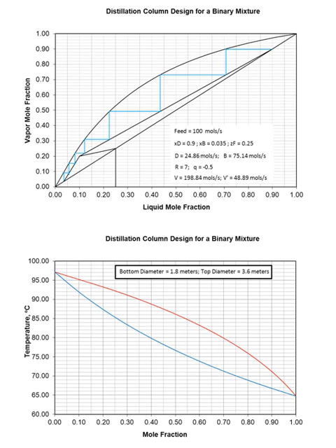Now we're going to look at doing an energy balance around the condenser. We have a vapor entering the condenser, and it's being transformed into a liquid at that pressure. And we need to know what the temperatures of both streams are. We can get this off of the vapor-liquid equilibrium curve and the temperature mole fraction curve. Knowing a distillate mole fraction is 0.9, we can project that value down to our temperature curve and learn what the temperatures of the vapor leaving the top of the column and the liquid leaving the condenser are.